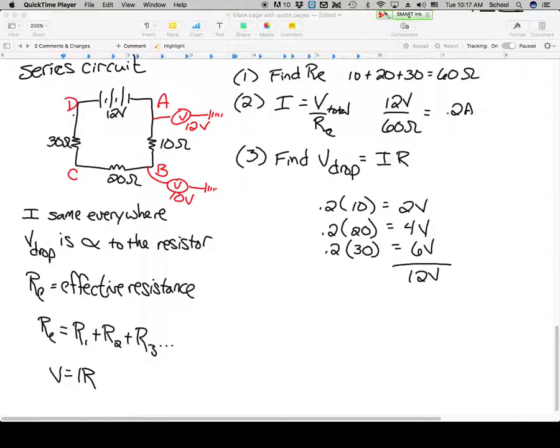If I would connect this one to a voltmeter and connect that, there's another way to make a ground symbol. It can also look like a little rake instead of a pointy arrow thing. But you see, if I connect C to ground, then that voltmeter would read 6 volts. And if I had a voltmeter connected to D and connected to ground, it would read nothing.